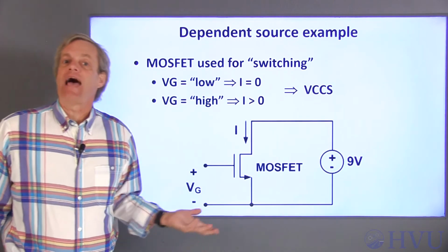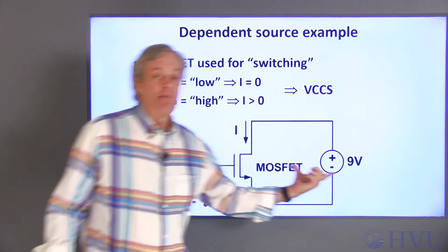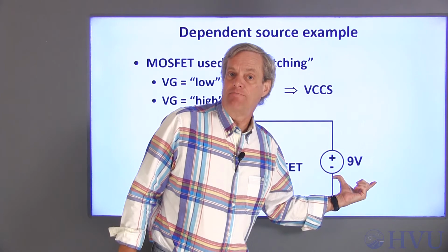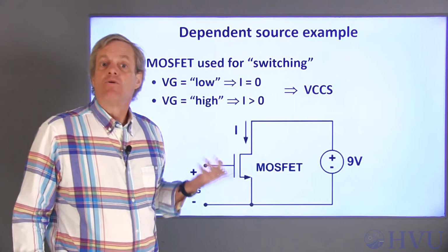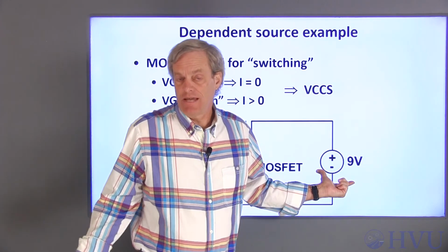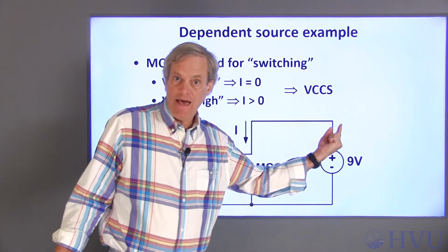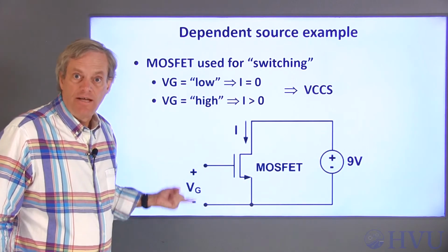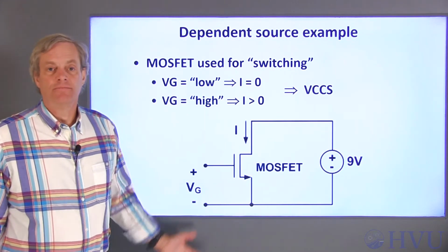Since the circuit's an active component, it provides power from an external source. I'm using a 9-volt battery to provide power. This dependent power supply requires an independent power supply to function, which in this case is the 9-volt battery. The circuit's controlling the current leaving the battery based on a voltage applied to the MOSFET. Now let's implement this circuit and see how it works.